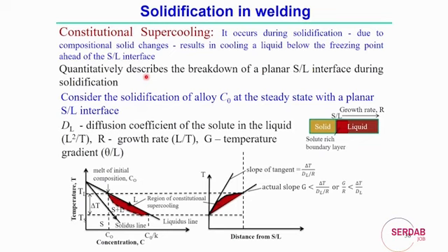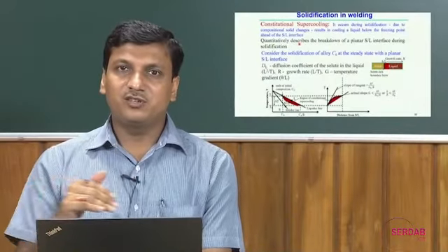So, during that transformation, there is an amount of supercooling observed in the liquid metal. Of course, it pertains to some conditions: before the start of the phase change, the nucleation mechanism involved in the welding or solidification process is governed by the amount of supercooling, that is, the temperature below the solid to liquid transition temperature.